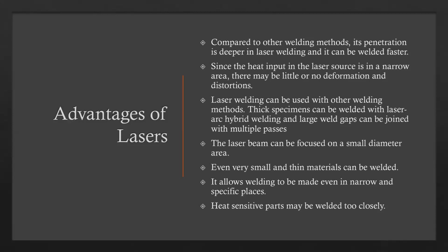Advantages of lasers. Compared to other welding methods, penetration is deeper in laser welding, and it can be welded faster. Since the heat input in the laser source is in a narrow area, there may be little or no deformation and distortion. Laser welding can be used with other welding methods. Fixed segments can be welded with laser arc hybrid welding, and large weld gaps can be joined with multiple passes.